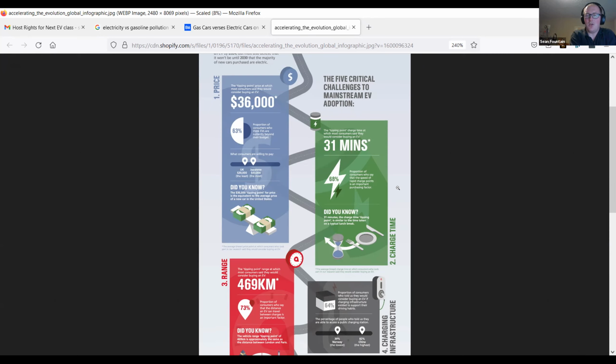To get an idea, in your home you're usually only running a handful of kilowatts, even with your refrigerator running and stuff like that. You maybe add a couple more when you're running the air conditioning and a couple when you're running your hot water heater. It's not a huge amount of power that you're using in your home. And to charge that 30 kilowatt hour pack in half an hour, you have to run roughly 60 kilowatts. So it's 2, 3, 4 homes worth of power to charge at that speed.